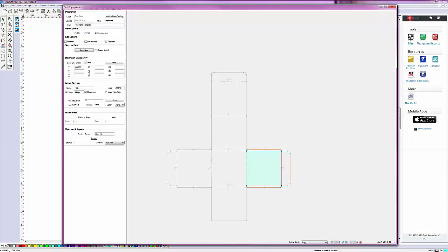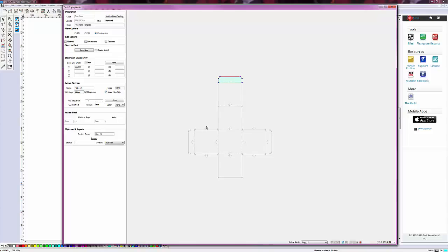Okay, retrying that. We now see that this section has become non-square, so we need to be a bit more thorough with our squareness flags, and we need also to maintain the shapes of the folding flaps and also of the glue flaps.